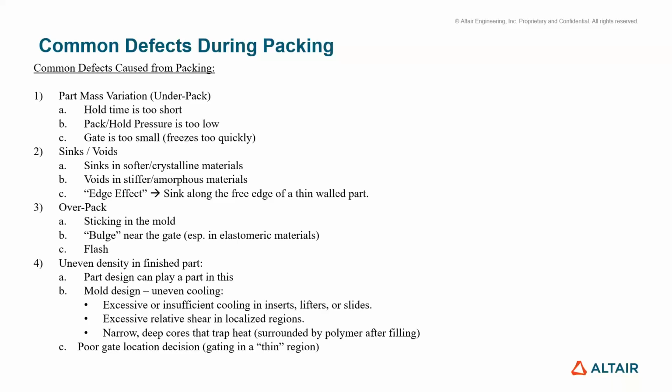You can pack longer without packing higher, and often achieve the effect you're really looking for. So pack until the gate freezes. Don't necessarily pack at the highest possible pressure you can put in there. You want to have even pressure through the cavity, not necessarily the highest you can get.